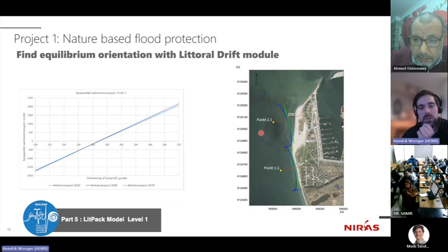But whether that's entirely correct or not is not necessarily known at that stage. So that just needs to be communicated and maybe reassessed at a later stage. If we rotate a shoreline around this point of the profile, and the changes are not very large, it's probably a minor error that we're introducing with the water depths along that profile.